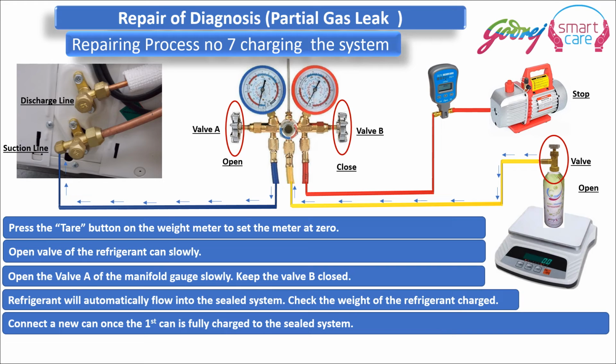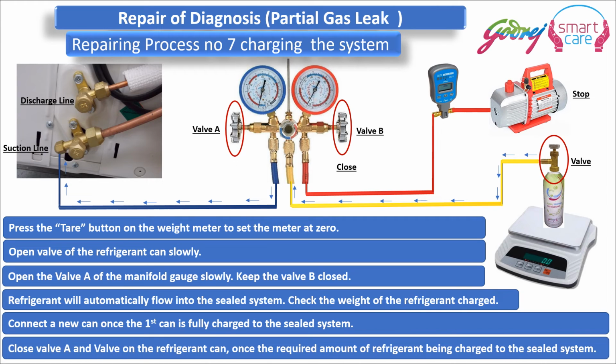If one can is empty and we still have to fill the refrigerant, we have to close the valve, remove the can, and fit another can.